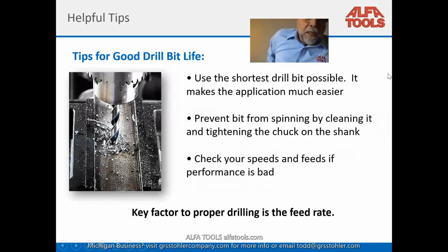Some other helpful tips for good drill life. Use the shortest drill possible. Prevent it from spinning in the chuck, which those 3 flats will do, or tighten the chuck properly. And check your speeds and feeds. The key factor in proper drilling is the feed rate. You know, heat kills, and if you're going in at the proper RPM, but you're pushing it too hard, whether it's with a drill press or by hand, you will prematurely dull out your tool.